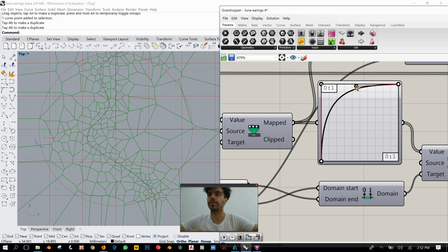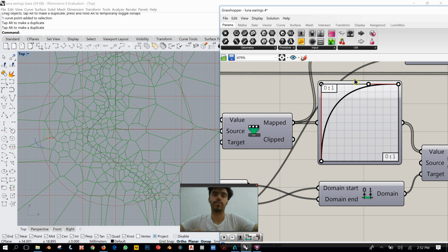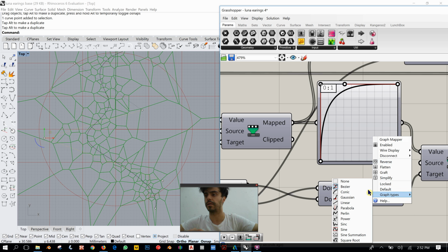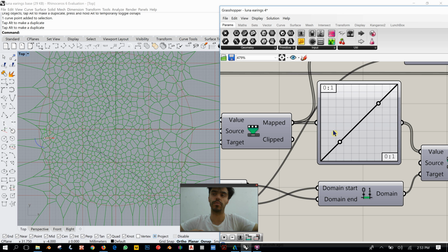It controls whether the smaller cells are just in the near proximity of this curve, or they become larger in a more linear way, rather than being here really close and then starting to be large fairly quickly when you move away from the curve. Because a linear way to represent this would be sort of like this.